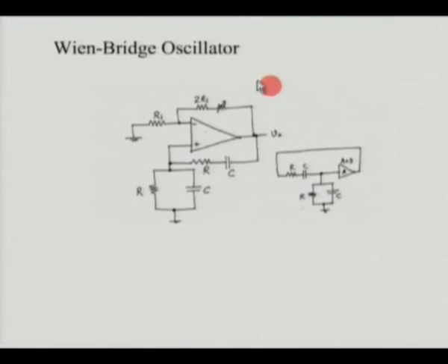Now let me come to this particular small resistor which we have put here. What we talked about was all ideal. We said that ideally the gain of this amplifier must be 3, but we know that we are using all passive elements here, capacitors and resistors. Now these resistors and capacitors will have losses. Therefore if you have exactly 3, you will never get oscillation.